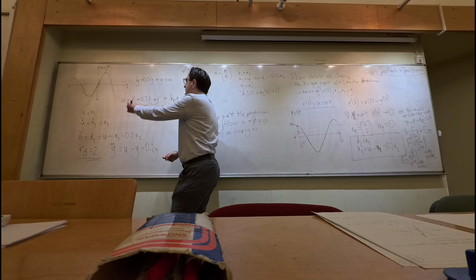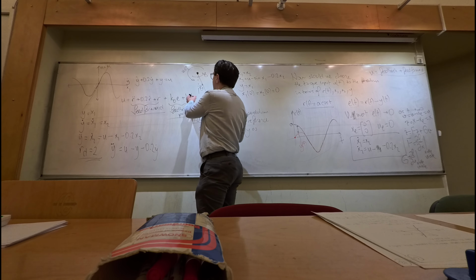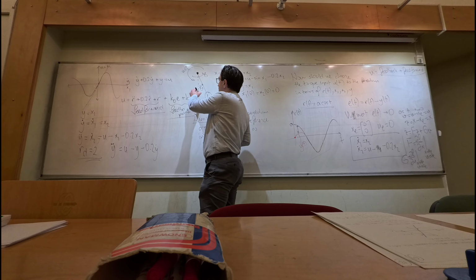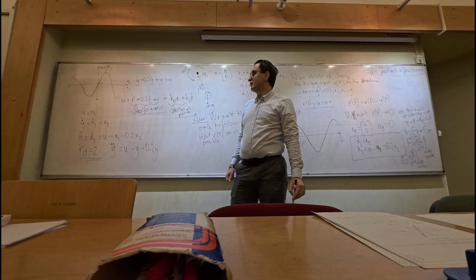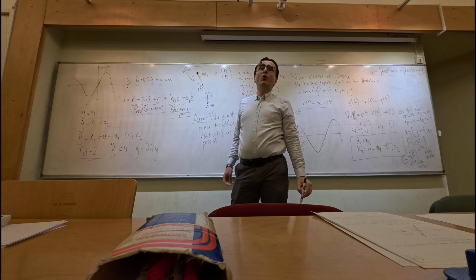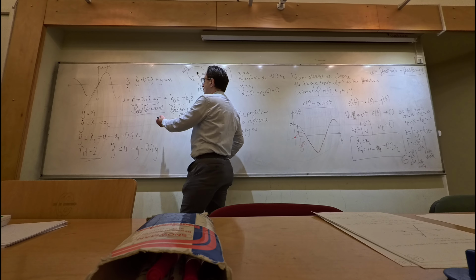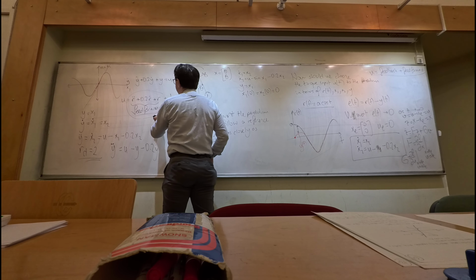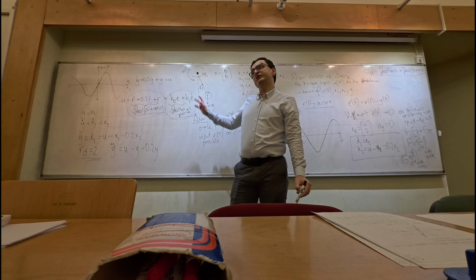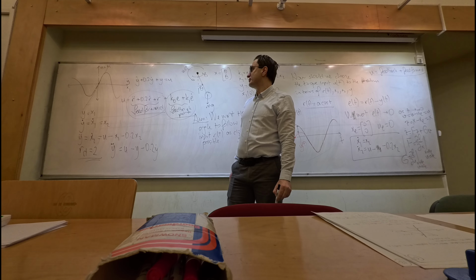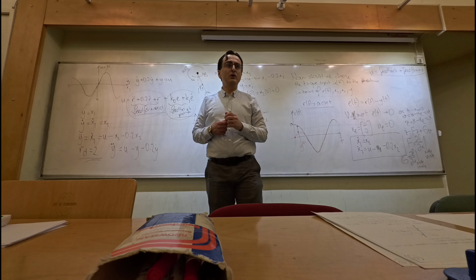If this equation contained a y triple dot, for example, I would have added one more term here as k2 times E double dot. That is how we form our controller, and it includes both a feed-forward controller and a feedback controller. We're going to see the effects of these parts when we go further on this topic.